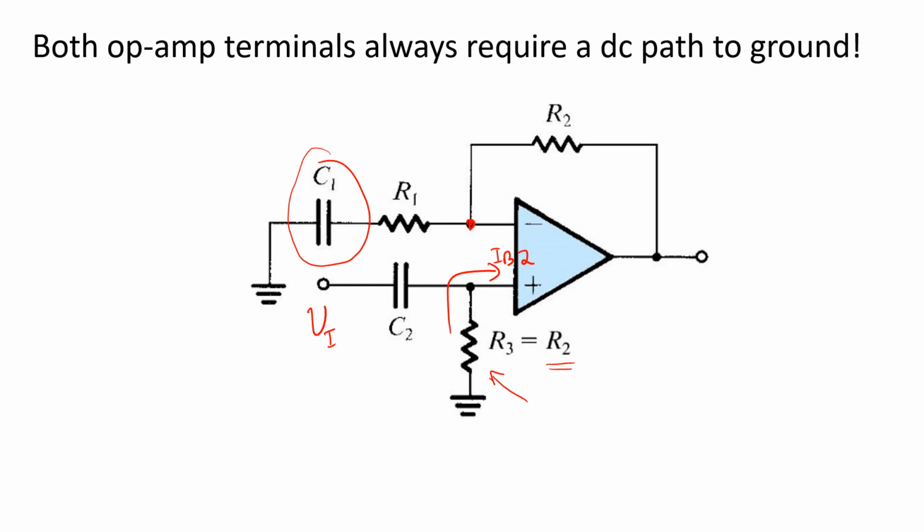So then the resistor R3 provides both a DC path for the input bias current to flow, while at the same time minimizing the impact of input bias current so that the output only depends on the input offset current. The downside here is that at frequencies that we're interested in, the capacitor C2 appears like a short.